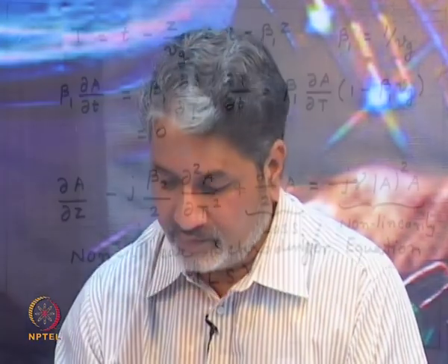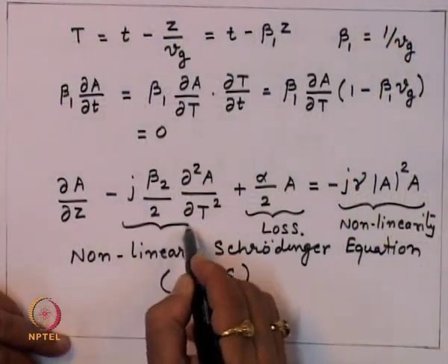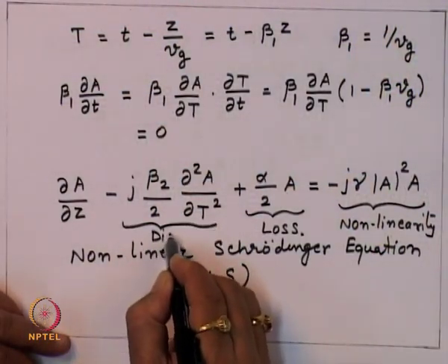We have seen dispersion which could be intrinsically because of material properties, that means the refractive index changes as a function of frequency, so different frequencies travel with different velocity, or it could be because of different modal propagation. But when different modes are not there, if the fiber is simply single mode, then different frequencies are still going to travel with different velocity, which we call monochromatic dispersion. That is what is captured by this term here. So, this term in this equation essentially represents the dispersion.